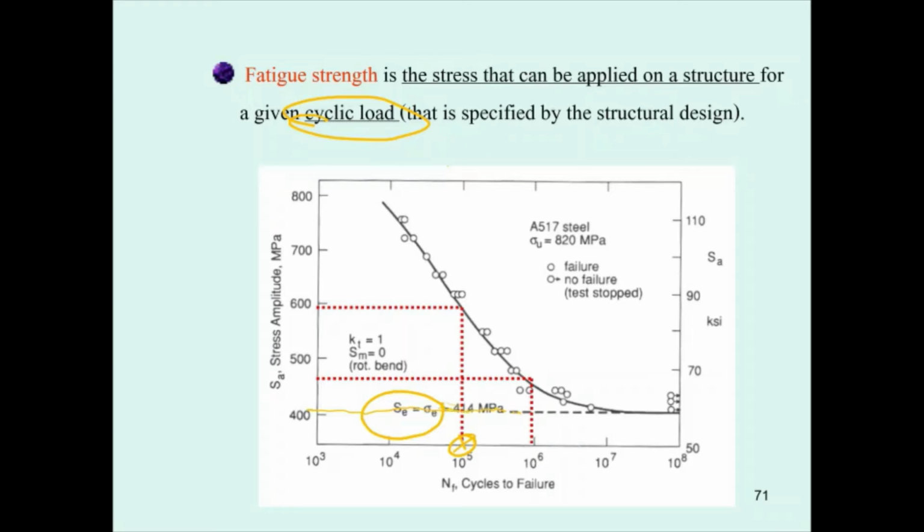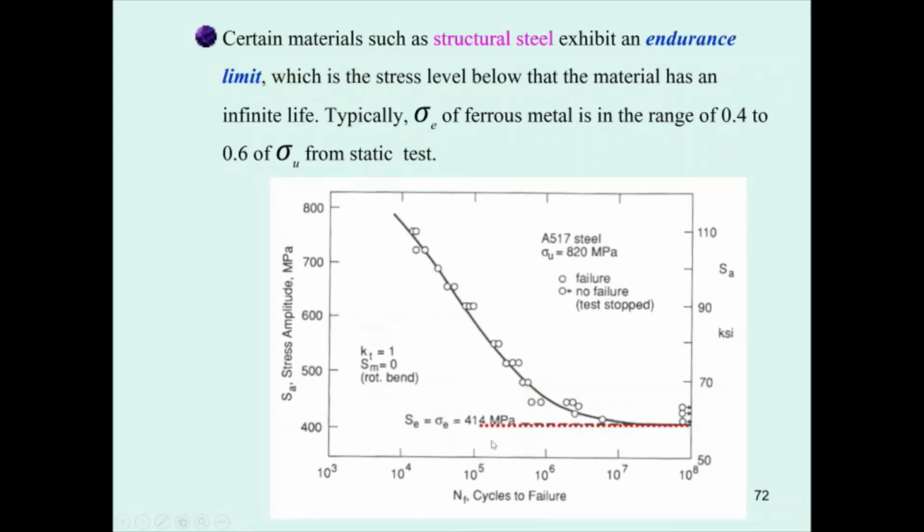Below this stress of 414, the material can take the stress infinitely. For some materials, like I said, there is an endurance limit, which is the stress below which the material can have infinite life.